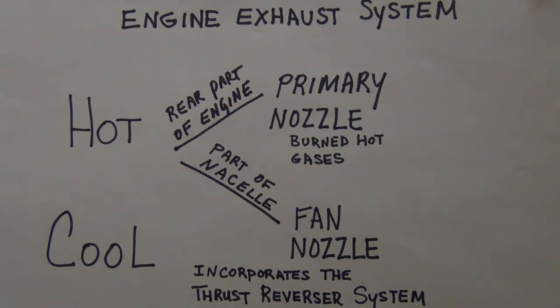Remember, I mentioned that before. FADEC is your full authority digital engine control. And part of that, you have your EIU, which is engine interface unit, as well as your ECU, which is your electronic control unit. Your actuation, remember I said your hydraulic power, actuates the actuators that are attached to the pivoting doors or blocker doors, and that allows it to be deployed.